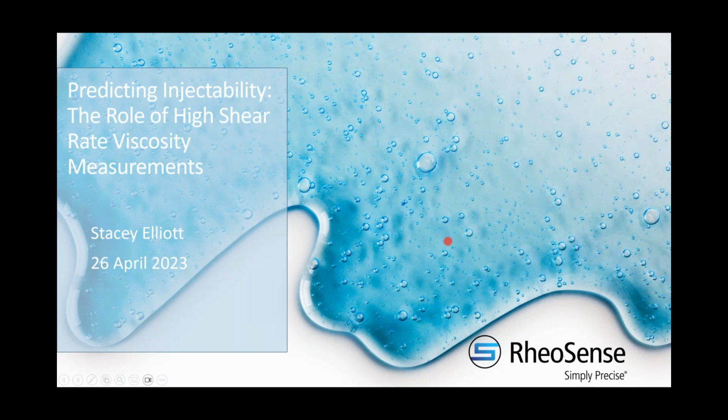And then also it's going to be dependent on the geometry of the system. So resistance will increase with increasing flow path length, and also increase with decreasing internal radius. And this is going to produce a pressure drop from the piston to the exit point.